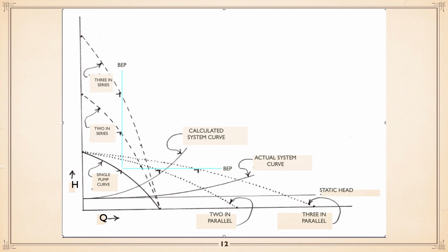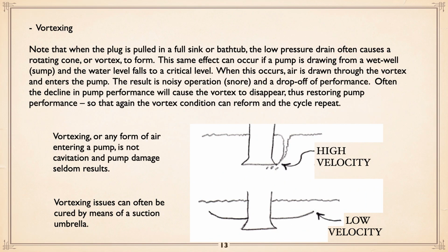problems are created. And of course, talking single pump curve, if you put two pumps in series, it doubles the head, capacity stays the same. Three stages, or three in series, will give you the third situation. Okay? Now, let's talk about vortexing.